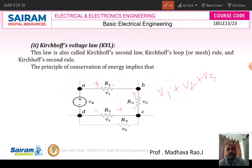Here take the current direction like this. Current entering the resistor you can consider plus, current leaving the resistor you can consider minus. So with this notation, V1 will be positive, V2 will be positive, V3 will be positive. Coming to the DA branch, here minus is there, minus VD is equal to 0. Algebraic sum of the voltage drops plus algebraic sum of the voltages in any closed circuit is equal to 0 at any instant. So this is about KVL.